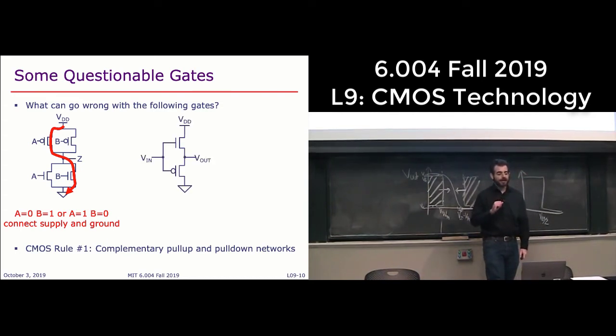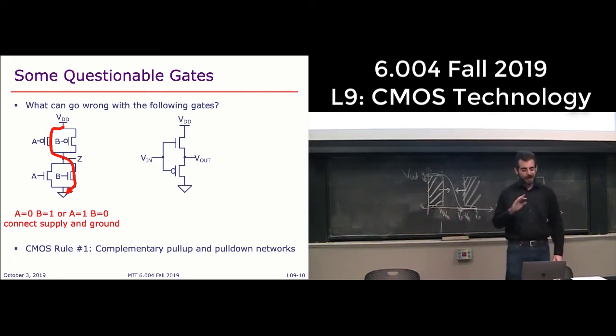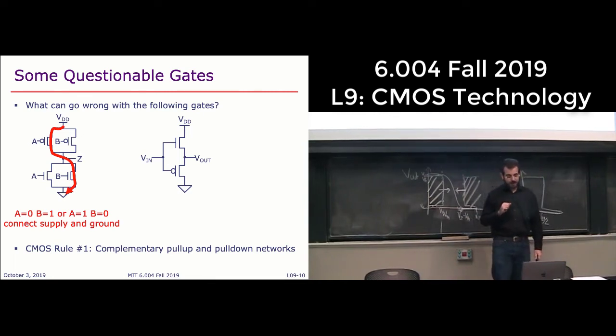This second gate over here is a little bit more subtle, and this is why you have to watch out for where is the source and where is the drain. So let's spend a minute analyzing this gate. If I just give you this gate and I give you the simplest possible rules, right? That high voltage here makes this NFET conduct, and a low voltage makes this PFET conduct. What function would you expect this gate to implement, this circuit to implement?